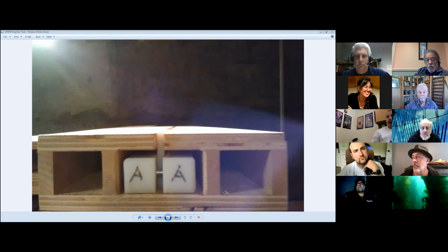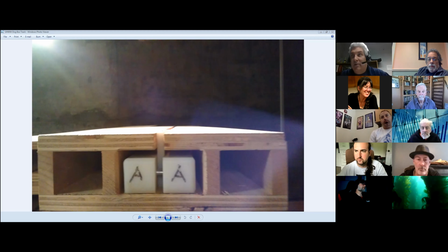Philip asked a question that I think's appropriate now. He says, what height are the deck boxes used with the dogs and knives that Chuck just showed? Good question. Our preferred standard off-the-shelf box, we build from 5/4 by 6 with 3/4 inch lids and a 1/4 inch finished surface. So you've got 1 inch and 5.5.